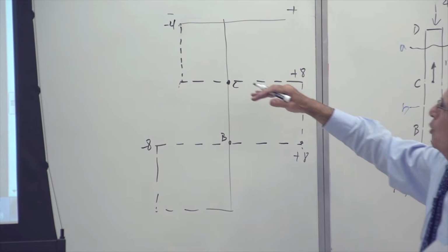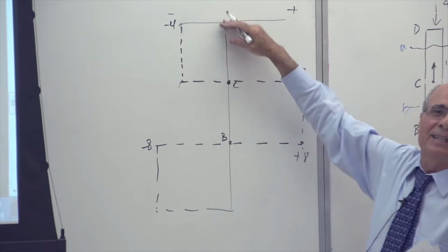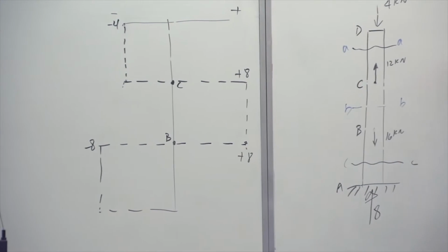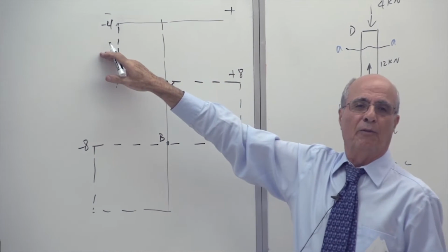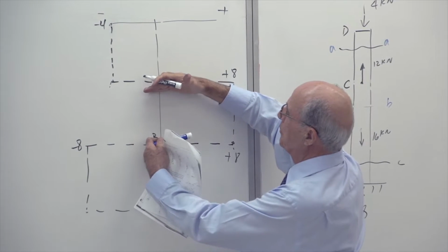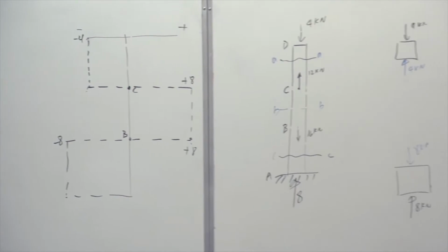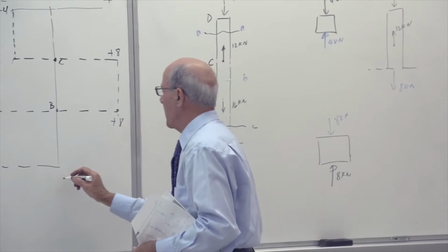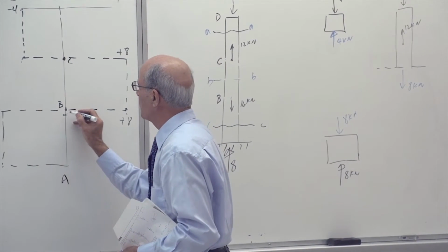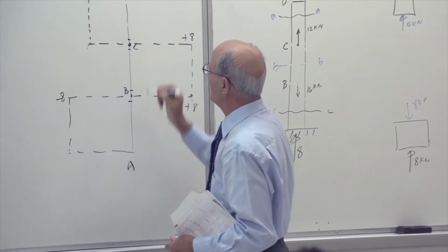An epsilon below, what's the force? The force is in member... Yes or no? The force is minus 4. For member CB, the force is plus 8. For the member AB, the force is here. You just have to stay an epsilon above and below this point.